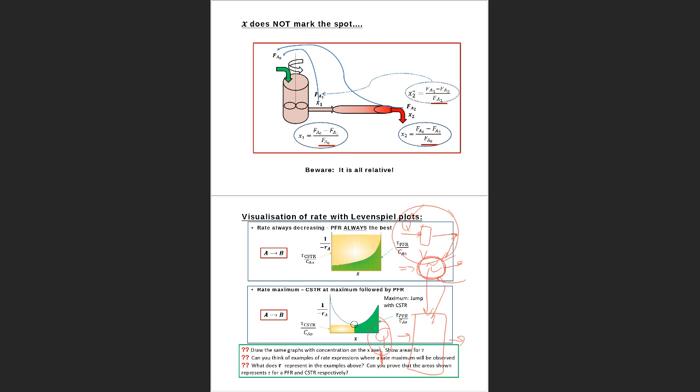Residence time, or we are going to use something like the weight hourly space velocity. It gives you a starting point for your design, heuristics if you want, to compare to what is typically in the literature. How long does this reaction need? And then for the detailed design, we will go to volume and mass of catalyst, detailed for your specific design. Does that make sense? Questions? Are you happy with that?